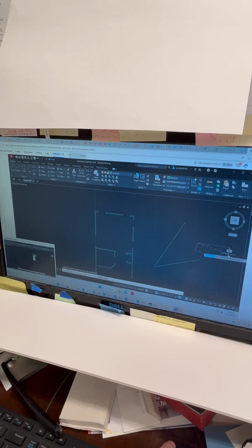Here, I can switch to angle. I don't even have to start over here. You just go ahead and select angle here, and then you can come over to whatever two lines you created. My two lines are at an angle of 63.69 degrees. By the way, you see the 2 points past the decimal point? That's this. Remember I told you it's what it's recording. All the dimensions also round to the nearest 32nd.